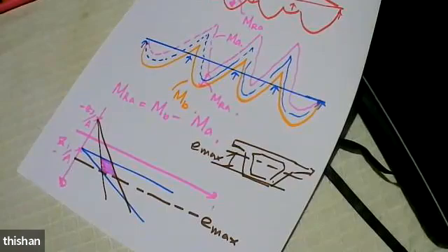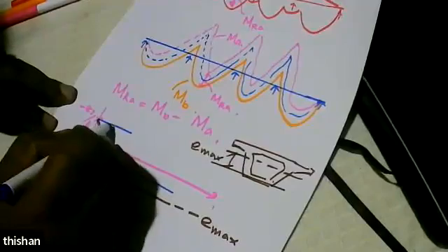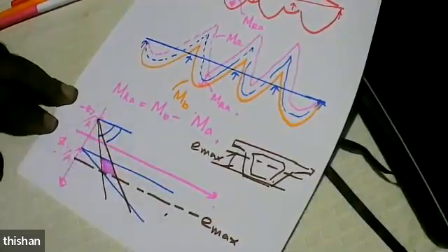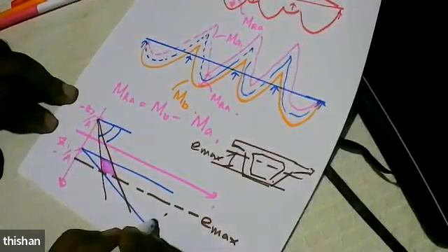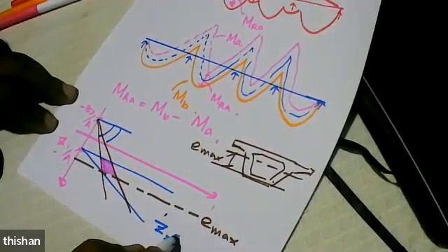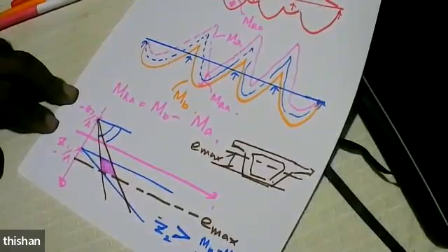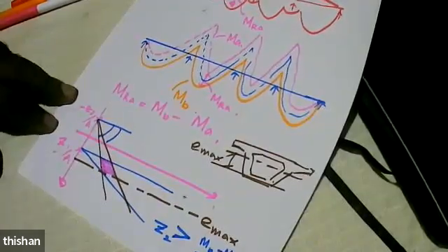And then we said there are some special conditions to be met. The gradient of this line should be greater than the gradient of this line. From that, we said Z2, a positive quantity, should be greater than MB minus MA over compressive stress under working minus tensile stress under working.